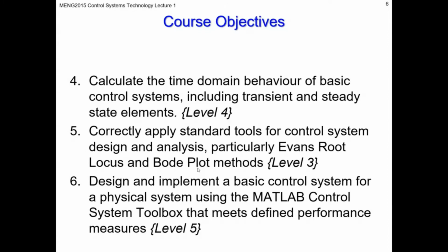They're available in the MATLAB control systems toolbox as well. So you can do the hand calcs in these cases, and also use MATLAB Simulink to generate root locus and Bode plots, and that allows you in both cases to interpret and understand how your system is behaving.